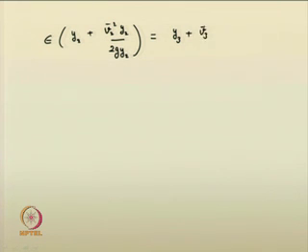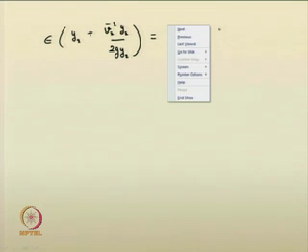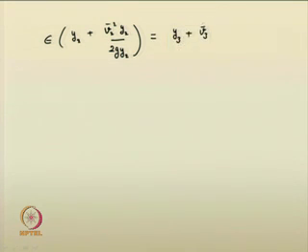The reason behind reducing is that we can eliminate y3 and y2 from the expression, and if we get the expression in terms of Froude numbers, it will be much better while designing. You can directly go with the Froude number aspects.